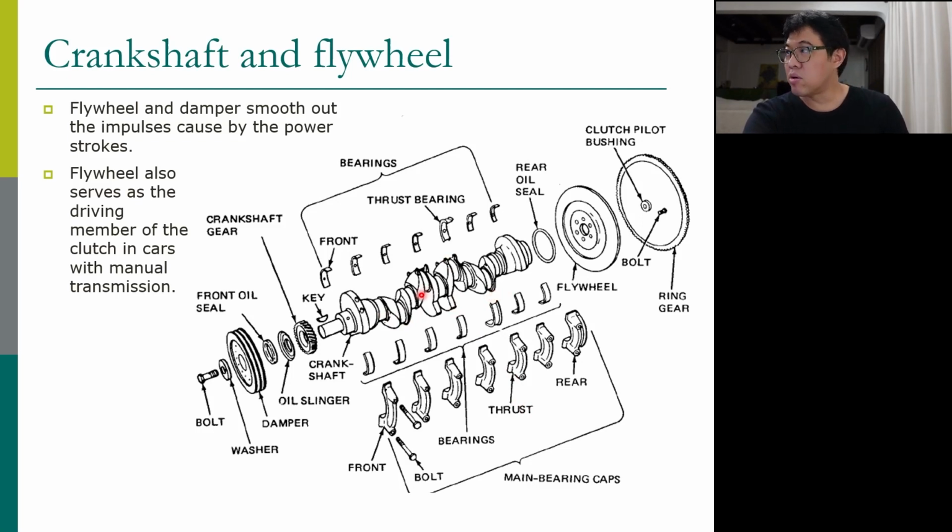Because the crankshaft gets power as a pulse from the piston, to complete one cycle takes two rounds. Down, up, two rounds. In two rounds there are four pulses; each cylinder has one pulse. Boom, boom, boom, boom. So the power is not smooth. The power comes as a pulse. It's like you are hitting the crankshaft like that.